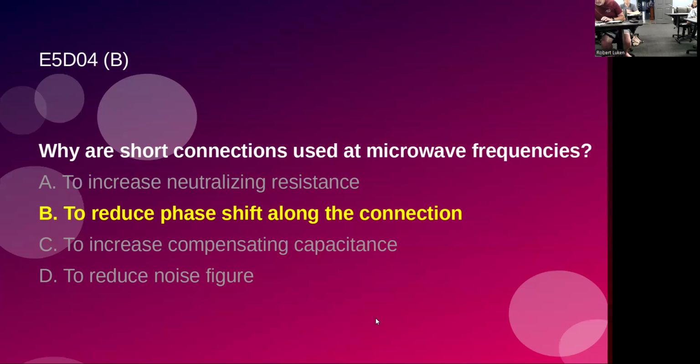And usually in those kinds of things, they will use what's called microstrip or stripline, where you're making a little transmission line that has a constant impedance by the width and thickness of it between the ground plane and the conductor, or it might be a sandwich where you've got a ground plane on both sides of it. Kind of like building a little coax.